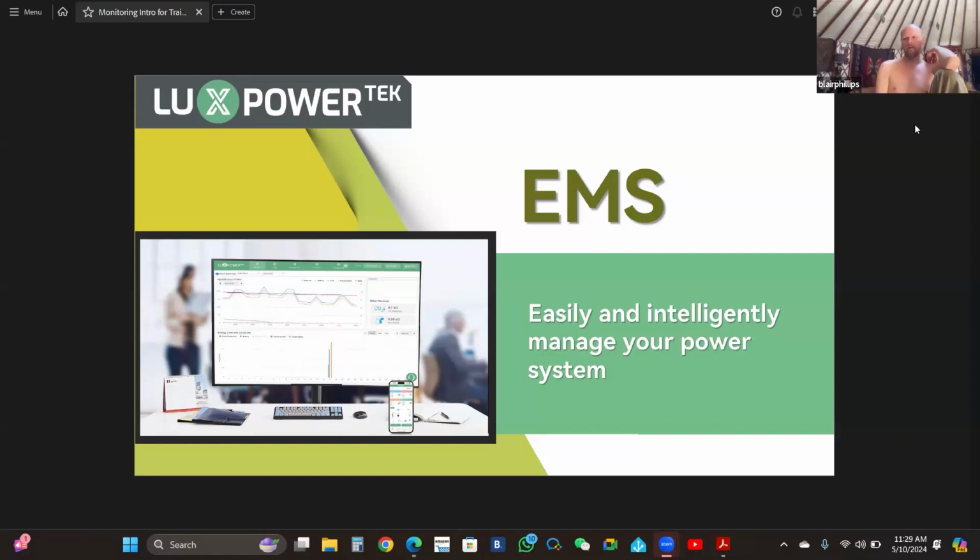And then with these systems that are grid intertied, do they ever need to be equalized? Not the lithium batteries. They have an inbuilt balancer that does that. Gotcha. Yes, only lead acid can be equalized, not lithium. I see.